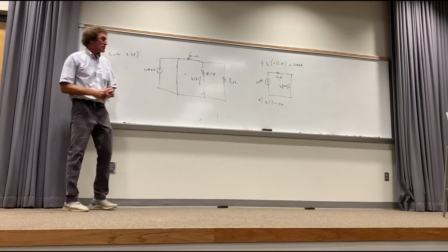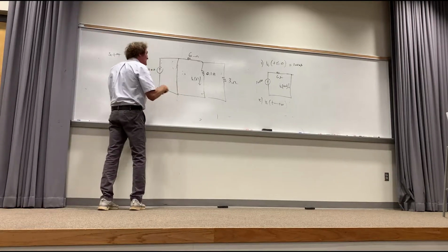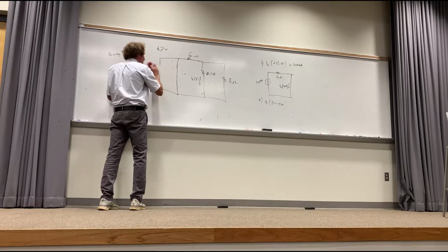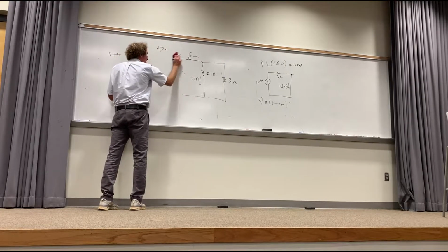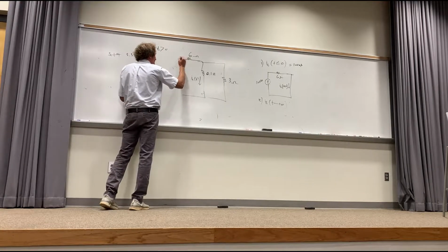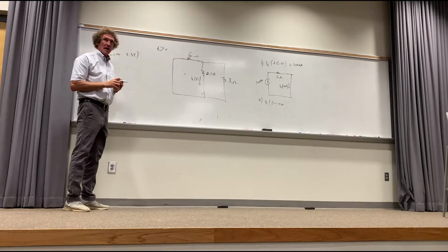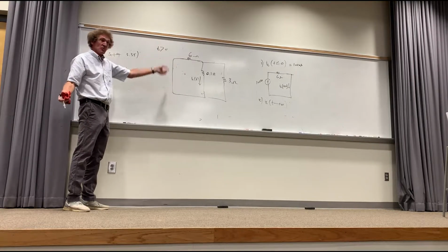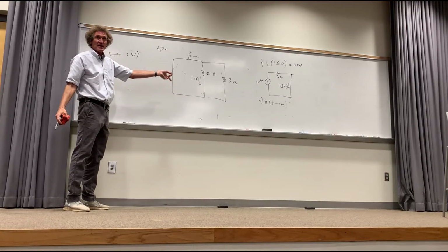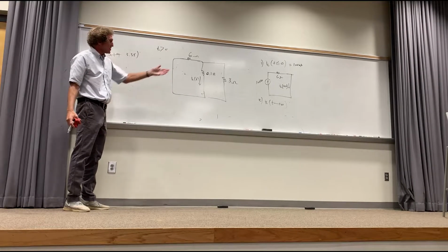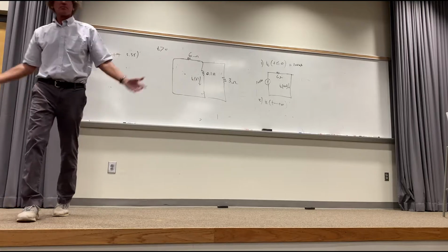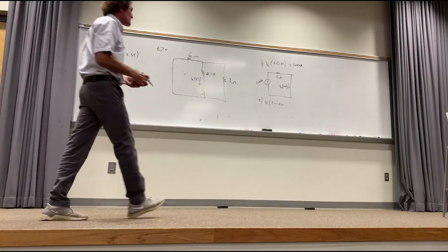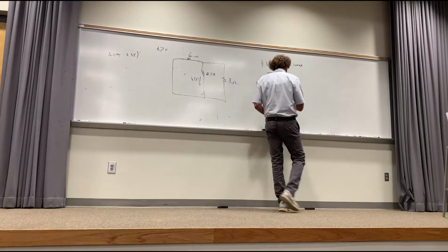So literally what you can do is this. You can just say, all right, I'm doing this for t greater than 0. Really, it's going to infinity. But since that's the case, to emphasize the point, I can just take that and short it, can't I? How many see that? Literally, because that was a short circuit when that shorts. Everybody got that? Now, if that's the case, are there any sources in there to sustain that current? None. What's the current going to go to? 0. That's right. So that goes to 0.